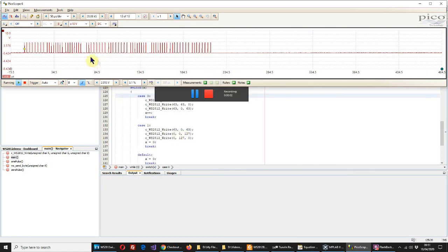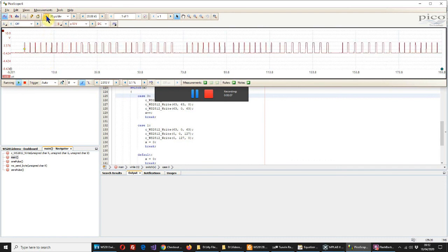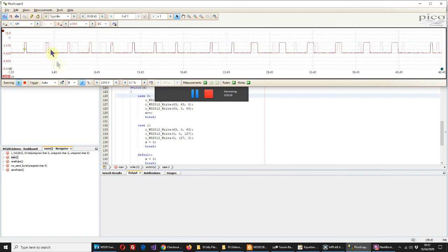The other thing I need to mention before I finish is the effect of interrupts on this code. If you run it as I am in this demo, in the background main loop of your program, any interrupts that happen in the high period of any of these pulses will ruin the timing of the LED data, and it won't work.